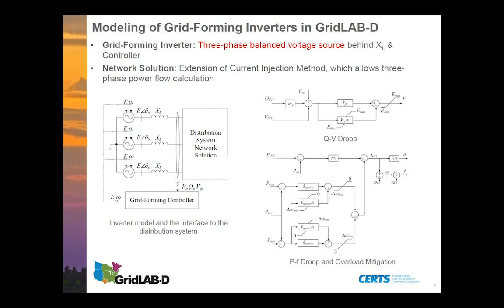Good question. As you rightly mentioned, when you're looking at the controller, especially grid following, you're looking at positive sequence detection. So what if you introduce a negative sequence control along with a positive sequence controller? Effectively, that's likely the means by which you have very good frequency response. In the grid forming mode, I'm assuming you're looking at the voltage being controlled, which means the current can be unbalanced.